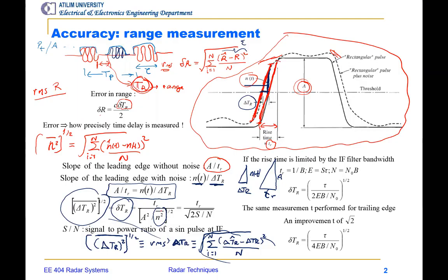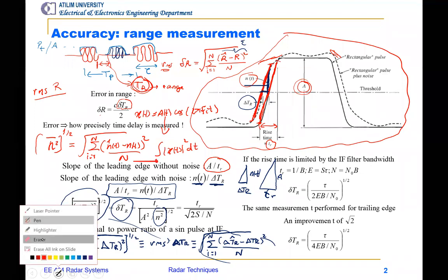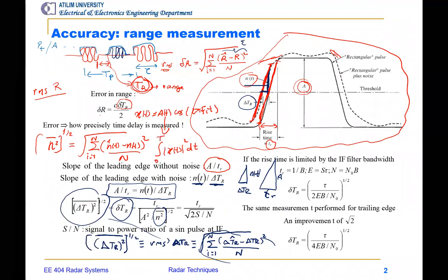Okay, we can write the signal power and amplitude relation by using a cosinusoid. Let's take, for example, x of t equals a of t cosine 2 pi fct, and then get its power. It's going to be the integral of x of t magnitude squared dt from 0 to the period T, and then the power is going to be a squared over 2.